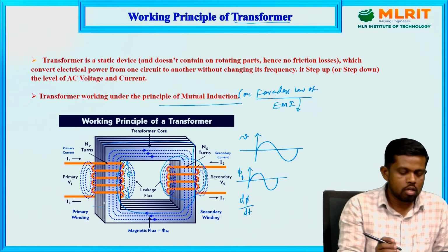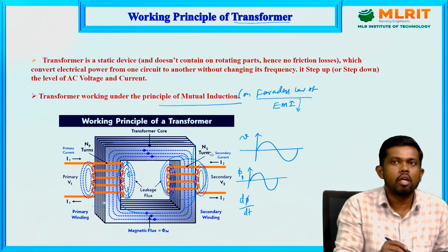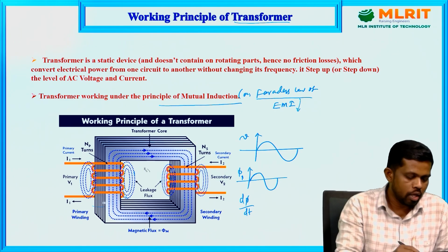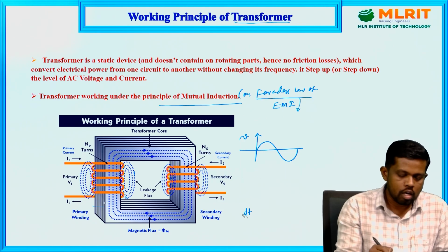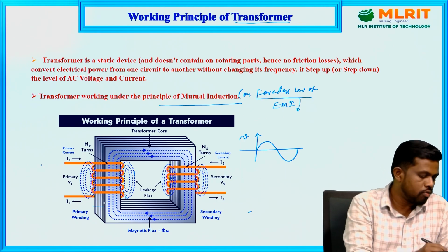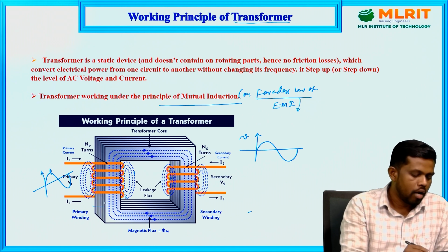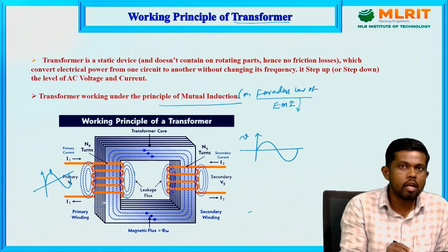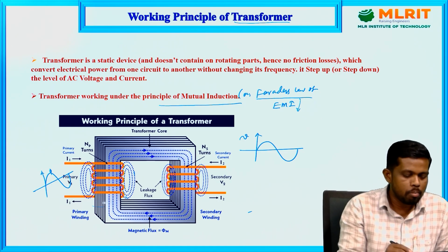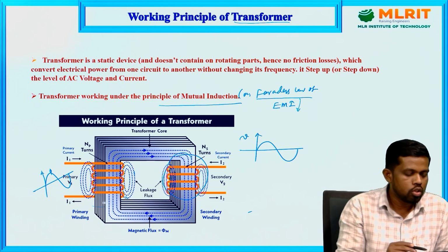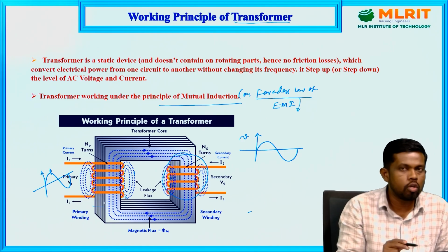Whenever the instantaneous or alternating flux is transferred uniformly to the entire core, it was created by this flux only. This instantaneous flux initially links to this coil and then transfers throughout the entire core of the transformer. There is also a possibility to get the EMF on the secondary side of the transformer winding. This whole process is said to be simply mutual induction.